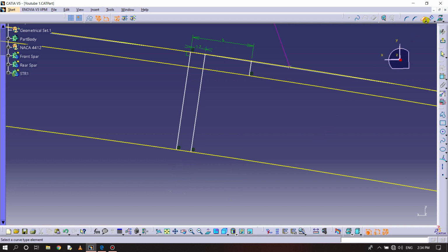Here is the one tricky part. We are using the command trim, so double click on it. Okay, so carefully select the lines, okay, and points are very crucial here. Press Ctrl and select this 1, 2, again click 3, 4, 5, 6, 7, 8, 9, 10, 11 and 12. Done.